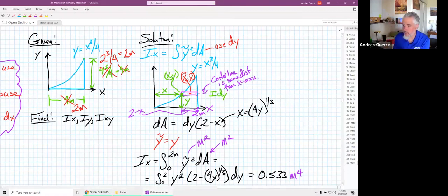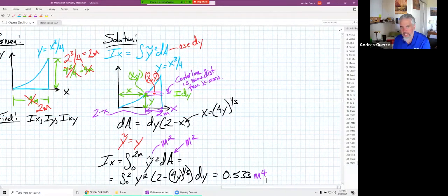And then, regarding the question in the chat there, just to check, the x tilde and y tilde are just the centers of the rectangle we are looking at. That is true. It is x tilde and y tilde, just where is the center of that rectangle, relative to the rest of the things that we know, symbolically relative to x and y and the equation that we're given. X tilde and y tilde are always the centroid of the individual rectangles.